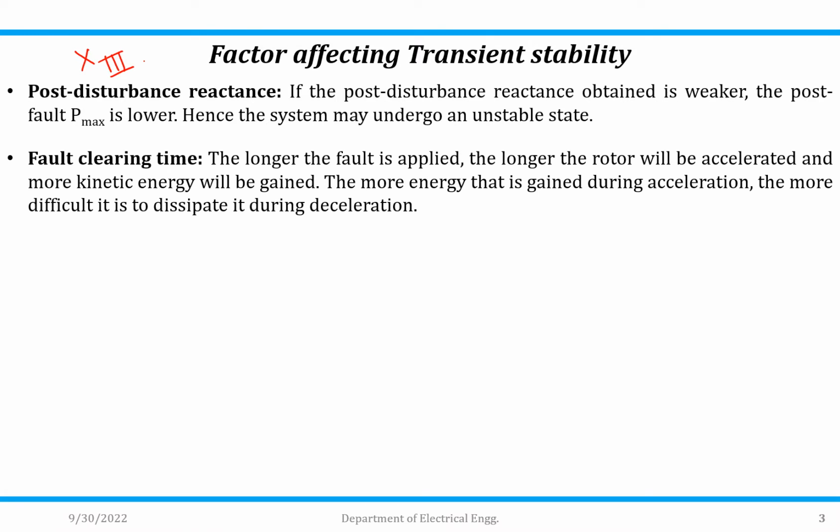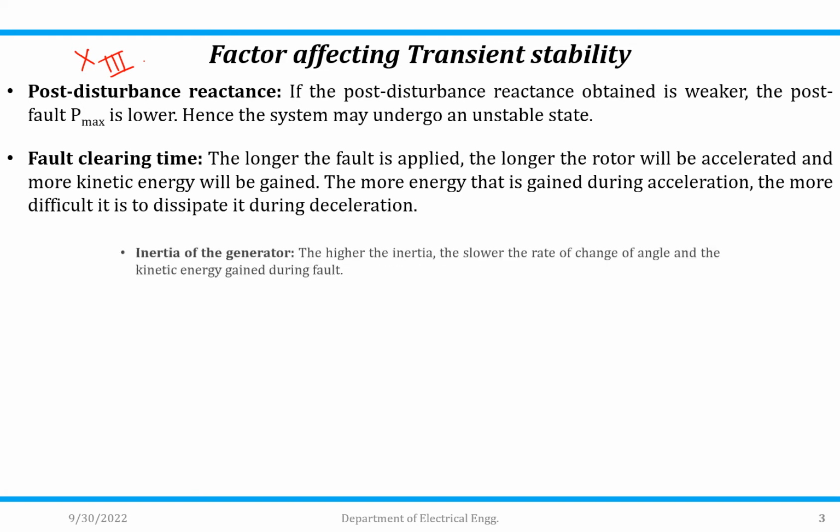The longer the fault is applied, the longer the rotor will be accelerated and more kinetic energy will be gained. The more energy gained during the acceleration, the more difficult it is to dissipate it during deceleration. So the fault clearing time should be as small as possible.